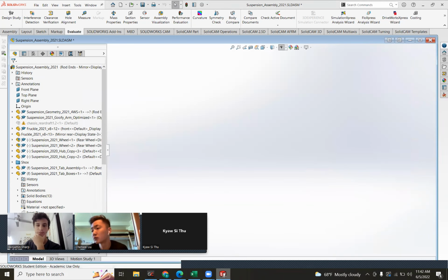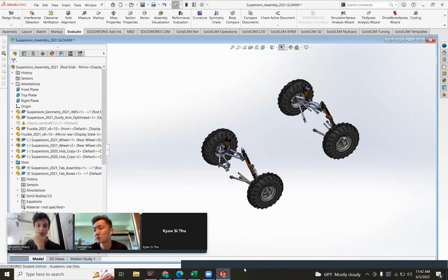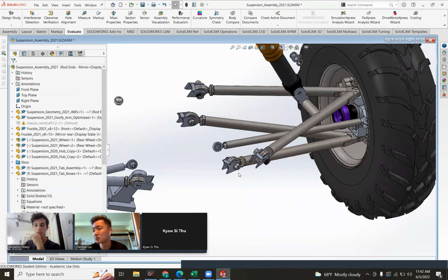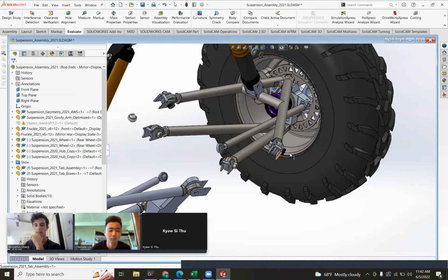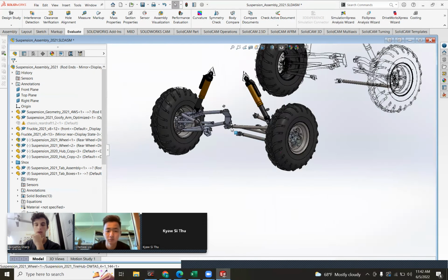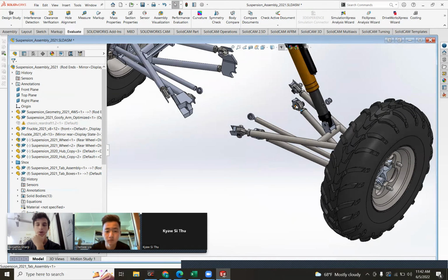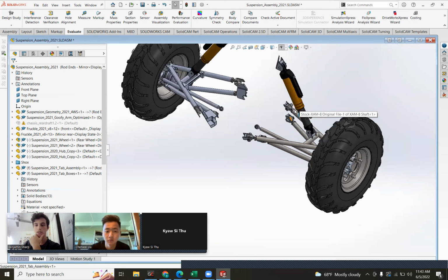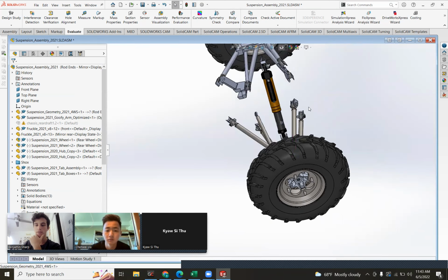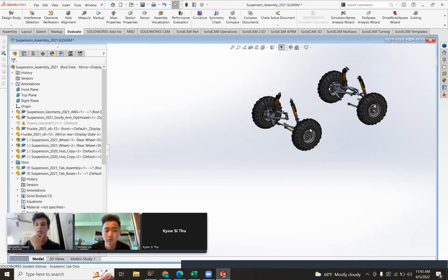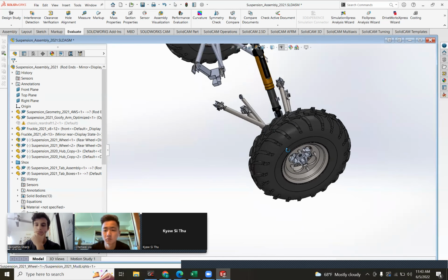Okay, chassis did something weird with their files, so we're just not going to fix it right now. But the lower tube, I just didn't have more room, because right after this point it started bending up towards the top of the footbox, and we didn't want to extend it more than we already had. And this point was already butting up against the bottom of the tube from the front bracing member, which ended here and then went all the way up to the top of the car. It's this one. If you can visualize that. It's so hard without the actual chassis though.